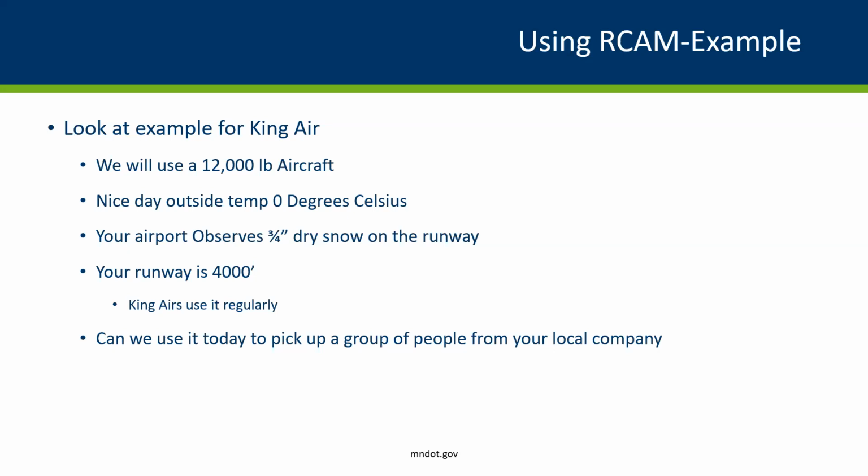We chose a King Air, and we're going to say this King Air is 12,000 pounds. It's a nice day at your airport. It's 0 degrees Celsius in the winter. And overnight, you know that it snowed, and you get out to your airport to do an airport check, and you notice that you've got 3/4 inches of dry snow on the runway. Not a huge deal, but you know, King Airs use your airport regularly. Maybe we use your airport regularly. So we want to see, can this King Air today get in there safely, knowing that we would be able to use this place regularly?